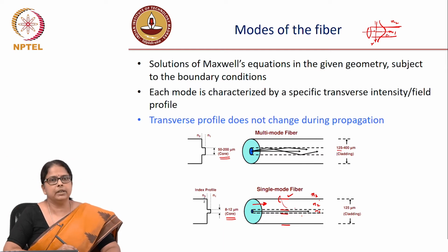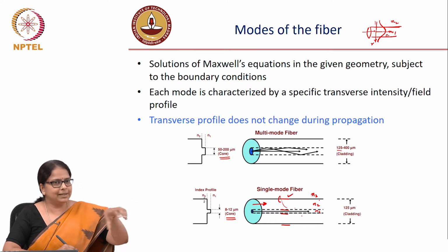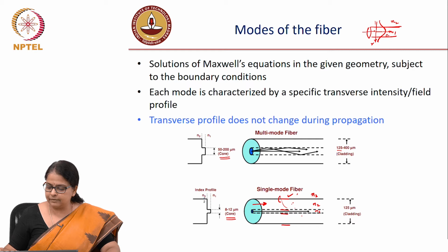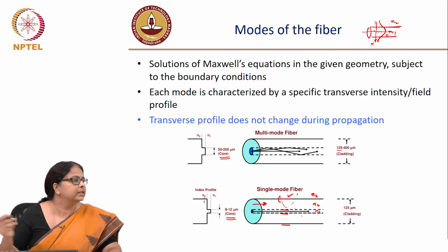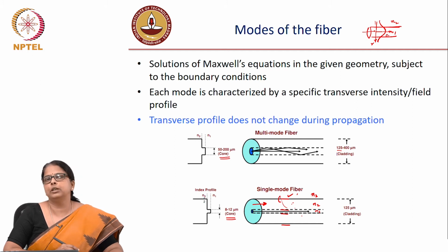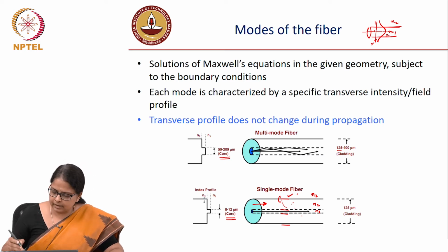For instance, if you are using fibers for making lasers, there is a class of fiber lasers where you are pumping the lasers by putting energy in the cladding, not in the core, right. So, there you have to worry about this interface and the cladding modes and so on. But in general, for communication applications, you do not really worry about the cladding-air interface, all your boundaries are core-cladding interface. So, this picture shows the refractive index profile.